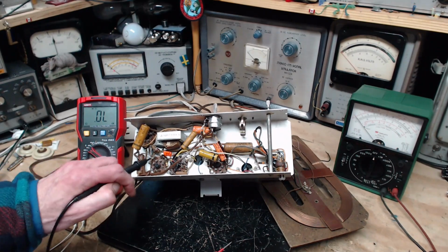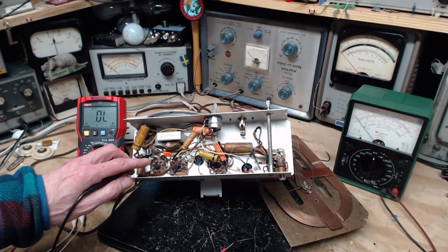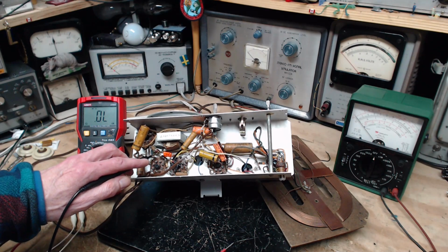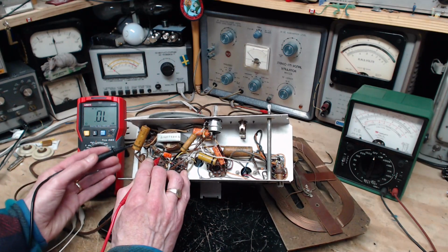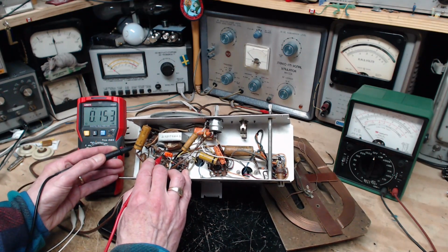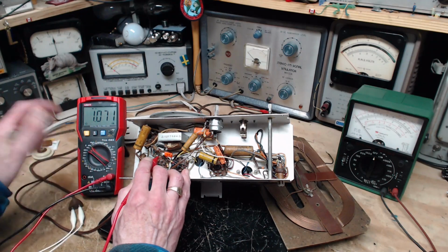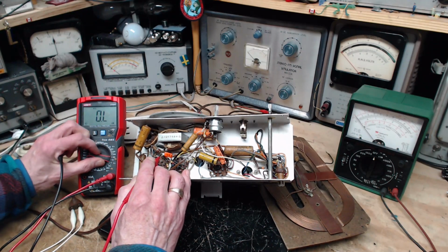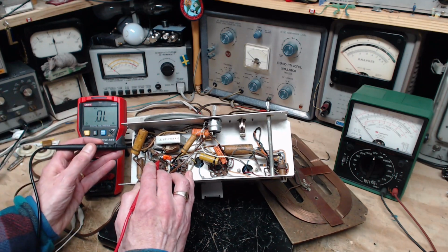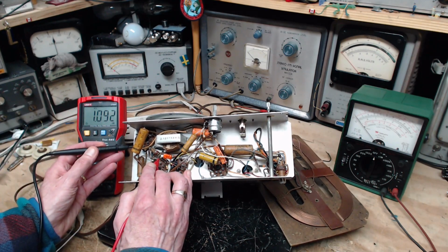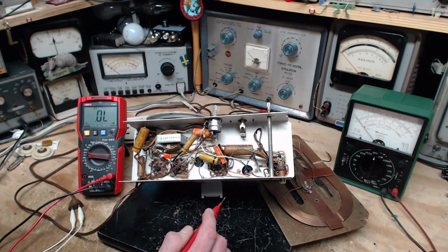This large resistor here, and the color is, I can't see it, black-red. This is probably brown, black-red. So this is a 1,000 ohm resistor here. Is it really? That's 1,000 on this scale. The only reason I'm checking this is because it's right here in front of my face, and I've got the ohm meter in my hand. So it's 1,100 instead of 1,000. That's probably fine.